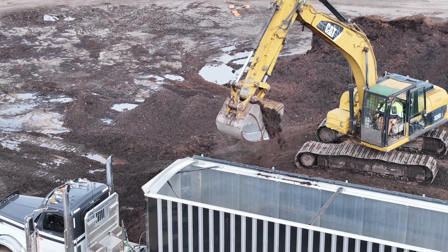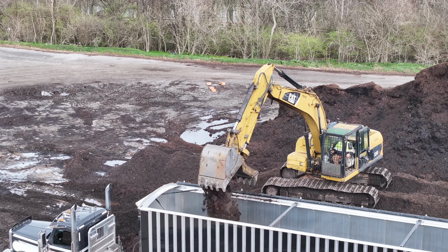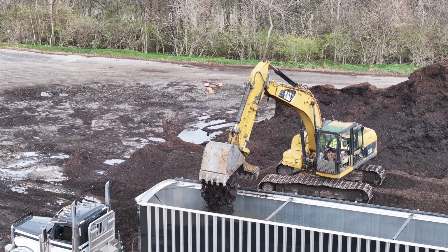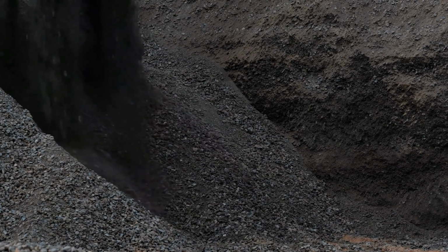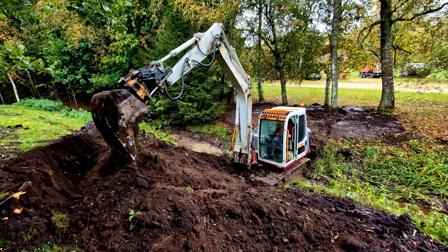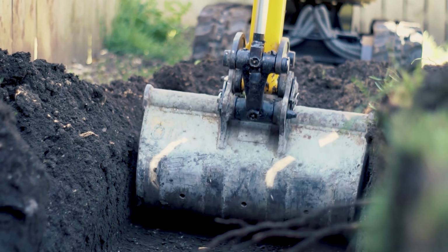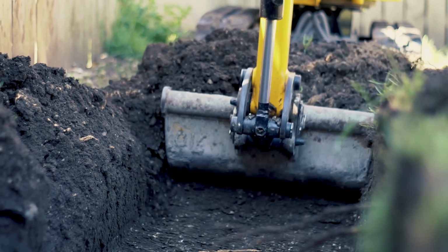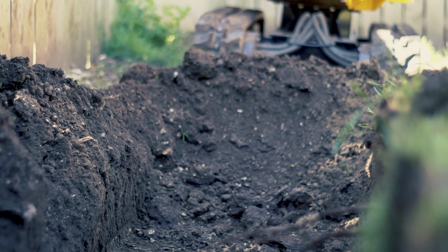The boom cylinder raises and lowers the entire front attachment, the arm cylinder controls the extension and retraction of the stick, and the bucket cylinder rotates the bucket during digging and dumping operations. Together, these cylinders coordinate to produce the powerful digging and lifting actions of the excavator. In modern excavators, hydraulic pressures typically range between 300 and 350 bar, which allows cylinders to produce forces of several hundred kilonewtons. However, the force at the bucket is not simply equal to the cylinder force.